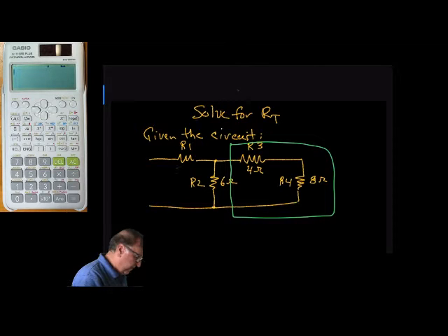That's the first step. So then we can combine these 2 resistors as they're actually in series. So we'll redraw the circuit, so basically the resistance here would be R in the box. We call this the box around the resistors. So R box is equal to 4 plus 8 ohms equals 12 ohms.